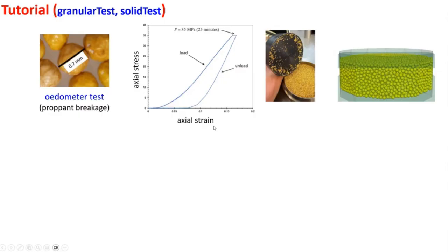You're applying the strain, right? And so as you push this down, when you load it, you get this stiffening. It basically starts to pack itself together. It kind of gets to a stable, packed state, has a certain slope. That's a measurement of the stiffness of the system, right?